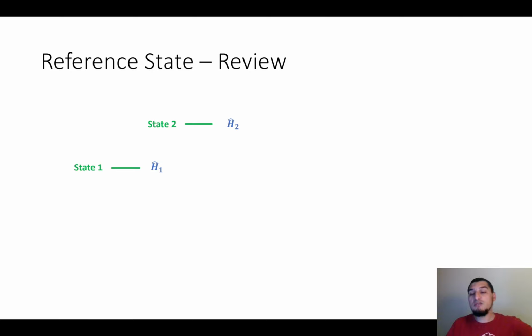The next point is the reference state. We talked about this in detail before in chapter 7, and we said that we cannot calculate the absolute value of the internal energy or enthalpy, because we cannot measure the actual value of the internal energy and accordingly the enthalpy. So we said we cannot calculate the absolute value, but we can calculate the difference between two values. And to do this, we have to set a reference state, a reference point, for which we consider the enthalpy is 0. And we calculate the two enthalpies, H1 and H2, relative to this standard state.